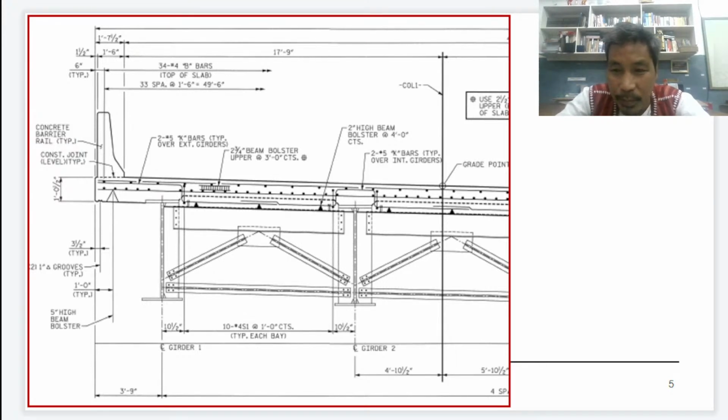The reinforcing bar is round or circular cross-section. Okay? But number 9 and above, those bigger bars, we are using square. Okay? We are using square in the computation. But in actual, those bars are circular. Right? That is another standard of practice code that only a civil engineer would know.